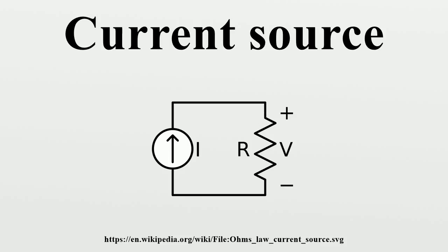Now imagine that the power dissipation in the transistor causes it to heat up. This causes the VBE drop to fall to, say, 0.2 V. Now the voltage across the emitter resistor is 0.8 V, twice what it was before the warm-up. This means that the collector current is now twice the design value. This is an extreme example of course, but serves to illustrate the issue.